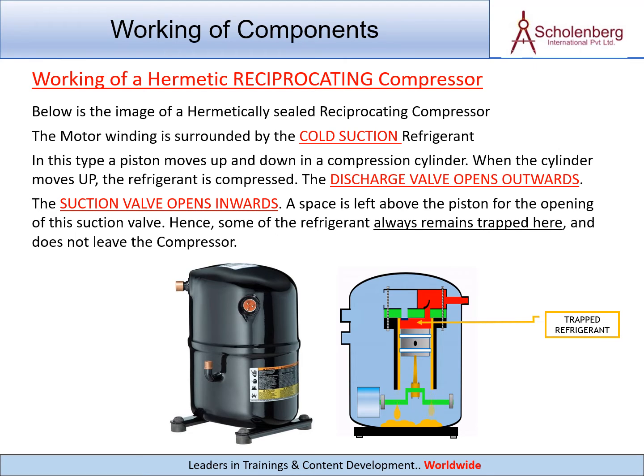The discharge valve opens outwards. The suction valve opens inwards. A space is left above the piston for the opening of the suction valve. Hence, some of the refrigerant always remains trapped here, and does not leave the compressor.